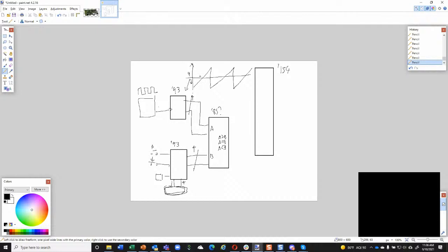And whenever A is less than B, the A less than B output is 1 during this time. So that's your pulse width. And you could OR that with equals if you wanted it to flip at the middle or before. So that's a PWM output right there, and that was PWM, not PMW. I must be thinking about cars. So that's your PWM output there that would drive a MOSFET.